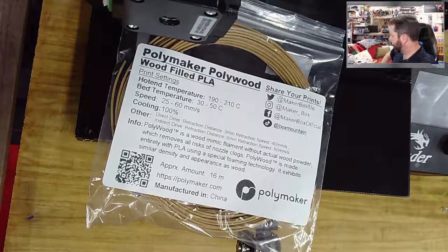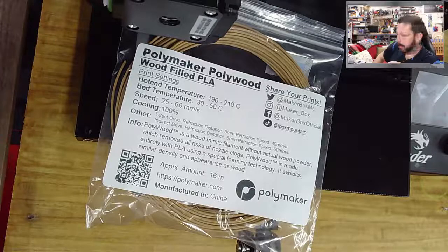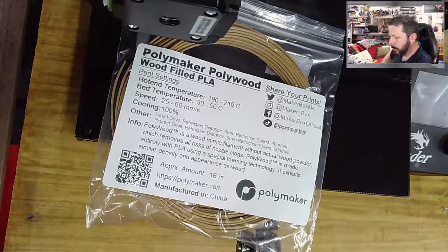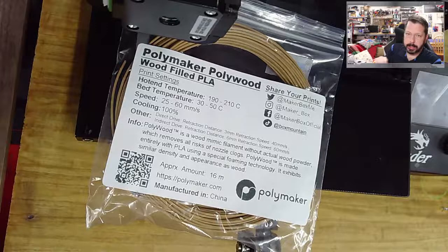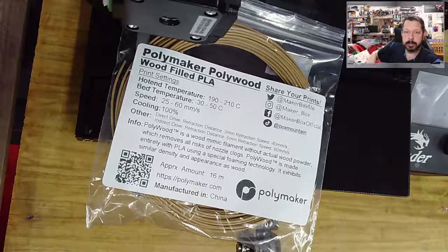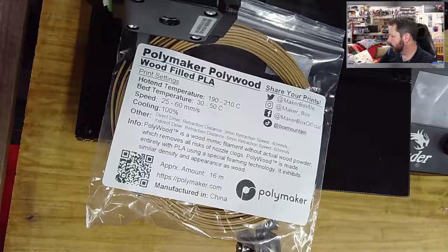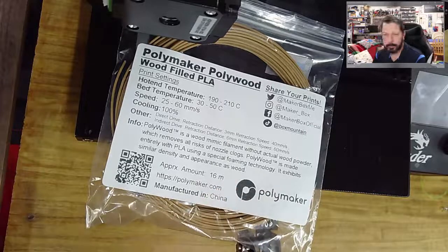There's another one of these that's a super lightweight PLA, and what it does is it actually foams up as you print it. I think I have some somewhere I'll have to find. It's really good if you're trying to print things like RC airplanes that need to be super lightweight, because once you've got it dialed in, you print it, and the heating causes it to foam up a little bit. You can get these really thick layer lines, but there's a lot of air in the layer, so it's a very lightweight material. I think that's what they're doing here, except they're using it to make it look kind of like wood.